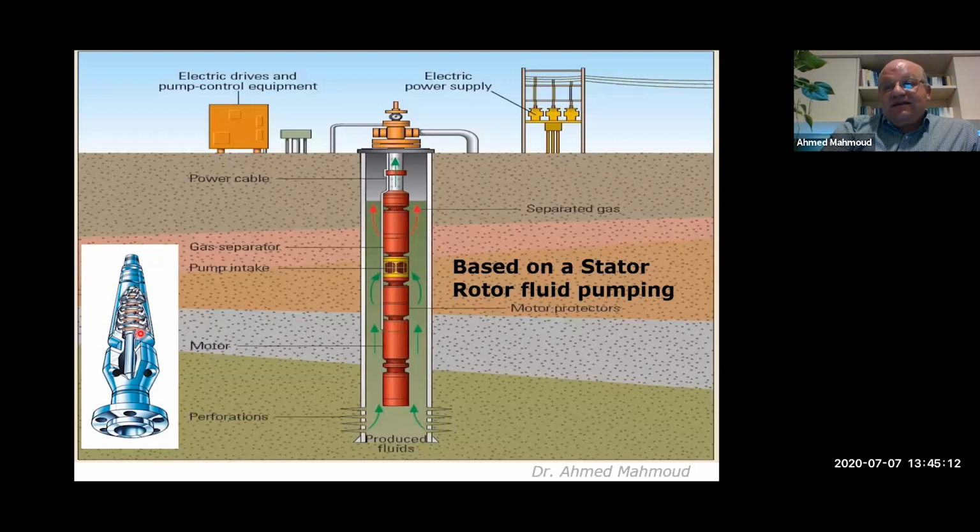And we'll see in the next slide the difference in performance you can have if you have a down thrust or an up thrust within these components. The actual ESP from the inside looks something similar to this, and basically you have multiple stages stacked on top of each other, and inside every stage there is a rotor and a stator applying a rotation.